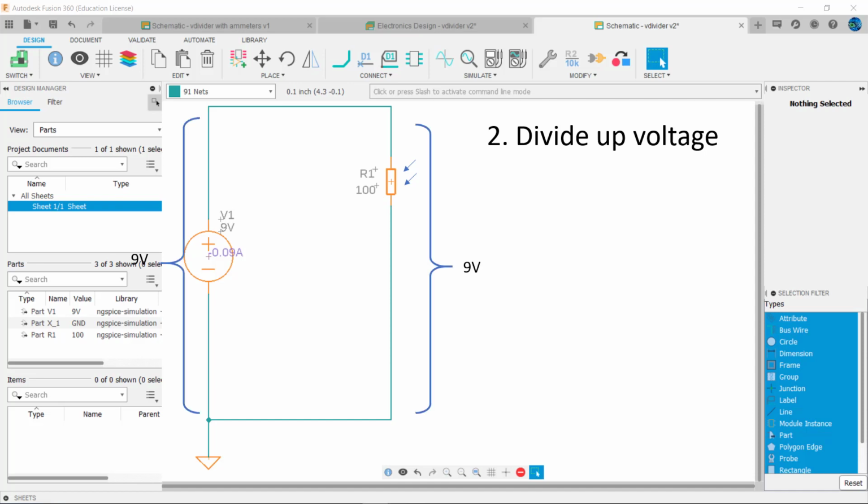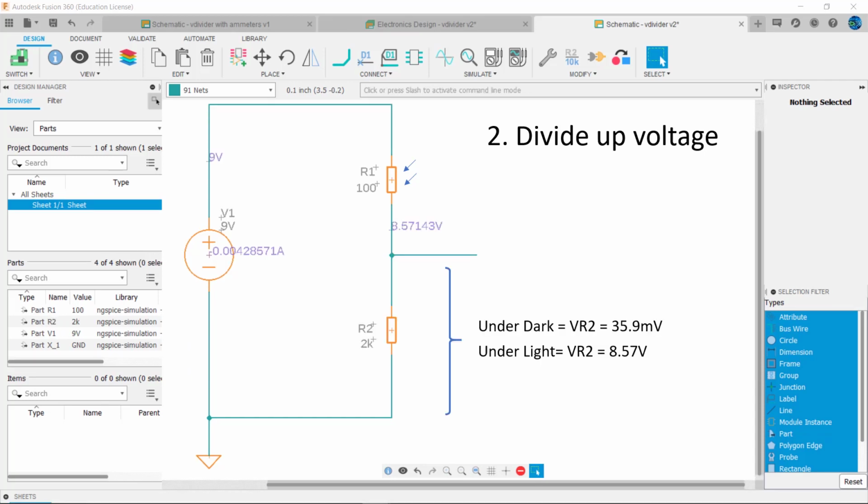Regardless of its resistance, we need another resistance to convert the change in current due to the change in resistance to a change in voltage. The addition of R2 provides a changing voltage in response to changing current caused by light striking the LDR. And this is the third application of resistors.